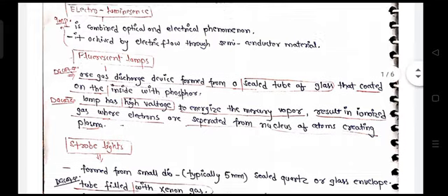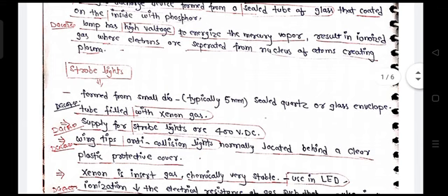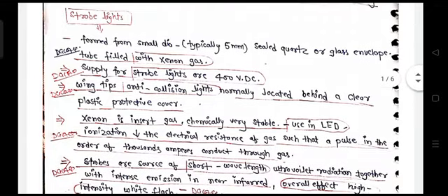Okay. Then you have got fluorescent lamps. What is fluorescent lamps? Fluorescent lamps is a type of tube lights only. The tube lights that we have used for so many years, the white color tube lights. Okay, it is a sealed glass tube, we know, and it is having what? The inside layer of the tube is having phosphor coated. Okay, and when you apply high voltage, what happens? There is a mercury vapor inside. That mercury vapor will ionize. Ions will form. Okay, mercury ions will form, and that will basically convert into a plasma form. Plasma is basically very high supercharged ions that will radiate a lot of light. Fine.